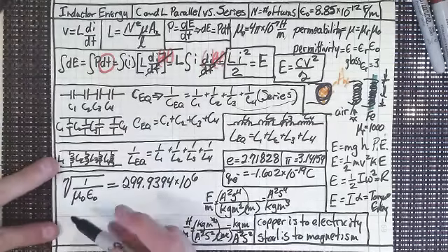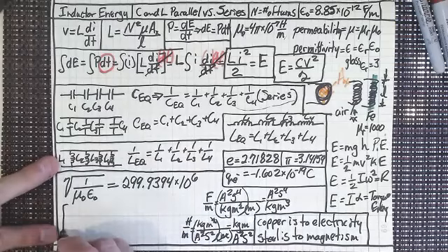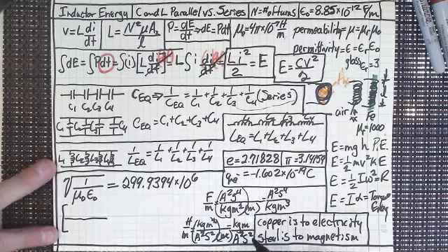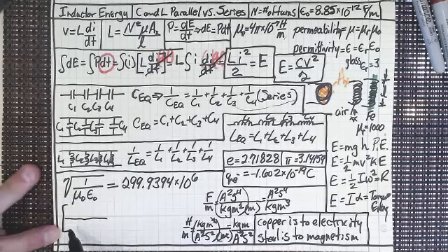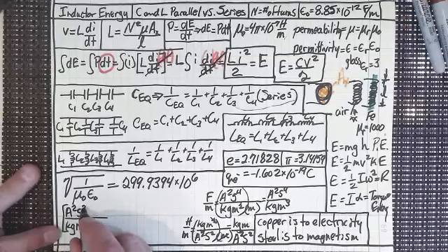Now, let's stick that in our thing here, right? Don't we just have a fraction? So the first one is henries per meter, but the henries are on the bottom, right? So I have to reciprocate this. So that would be a kilogram meter per amp squared second squared, right?